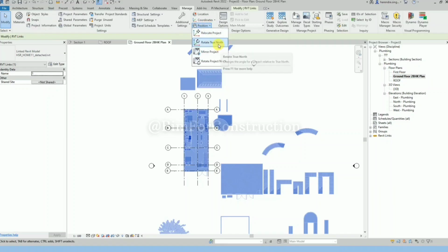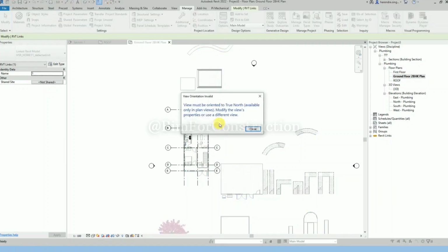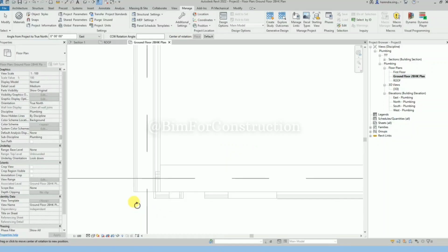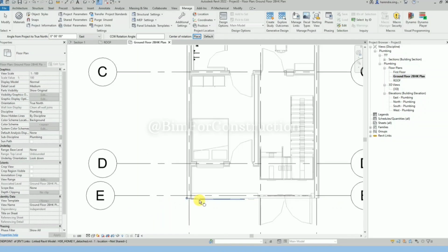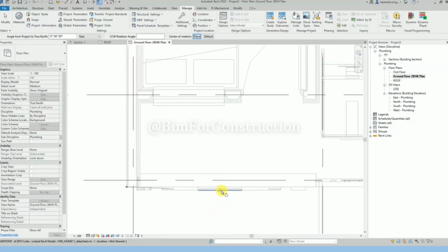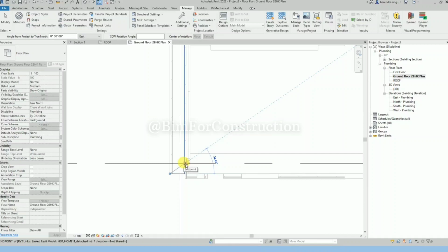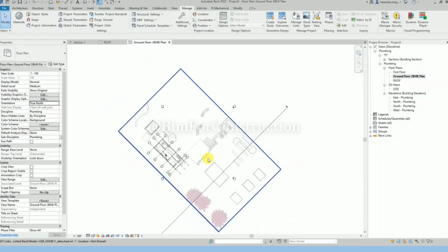So what we do, we rotate those buildings in our Revit project by any degree in which the building gives a better view to work, and you can set that view in the project north. Whenever you set the current view back to true north, it will again show you the actual rotation of the building, how it is on site. But when you select project north again, it will appear straight to you.